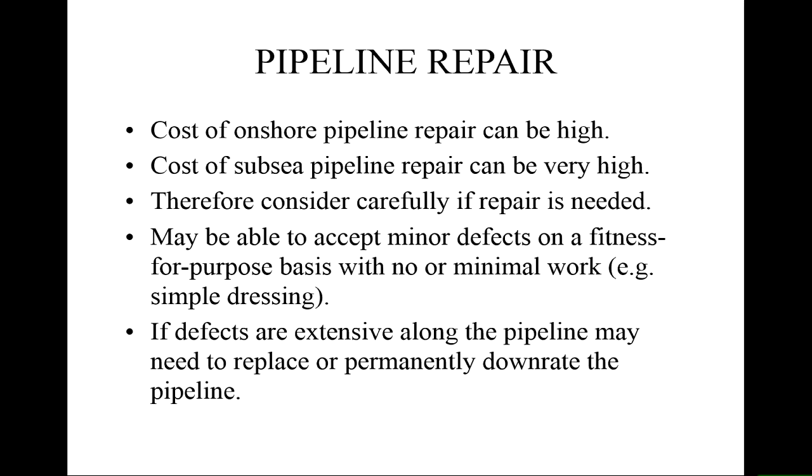If we accept some defects, obviously we need to know many details about them, how extensive they are, what is the stress state around these defects, etc. Then perhaps we can do nothing, or some simple dressing, like for instance a weld to remove the high stresses.